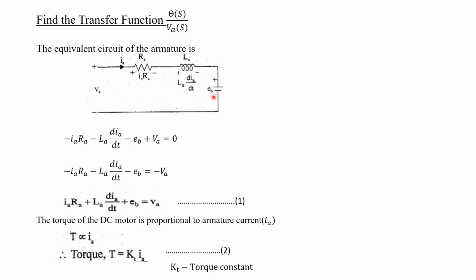So we are going from plus to minus, so minus Eb. Now when we are coming like this, it is minus to plus. So we start the loop from here, isn't it? Now after going through these parts, again we are ending here. So we are coming from here to here. It is minus to plus, so this will be plus. That is considered as voltage rise. The voltage value is Va. That is equal to 0.